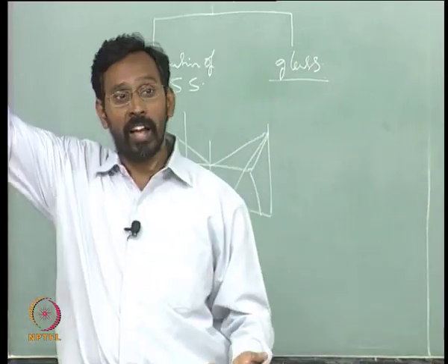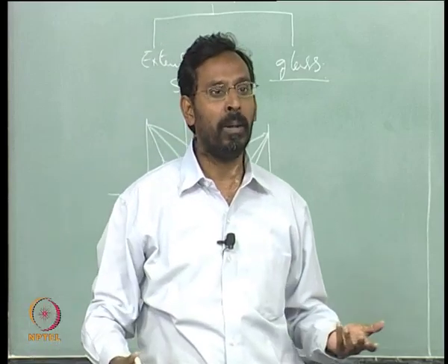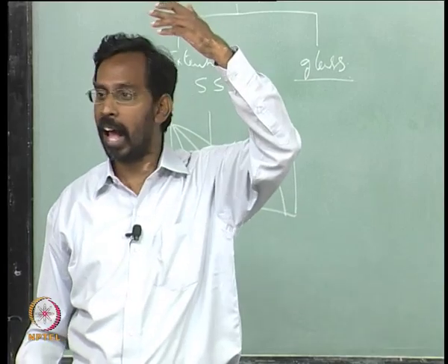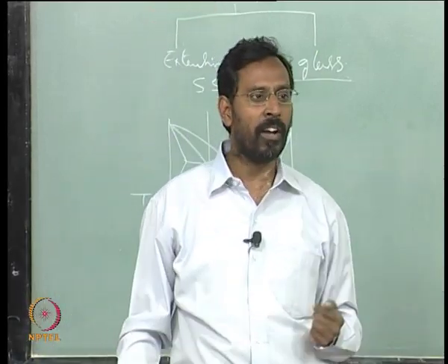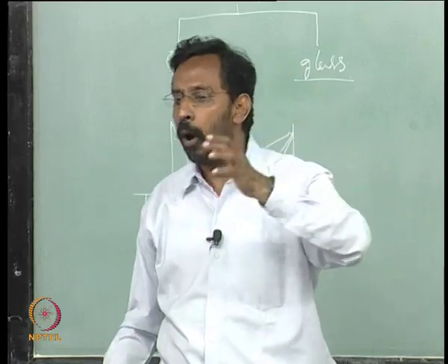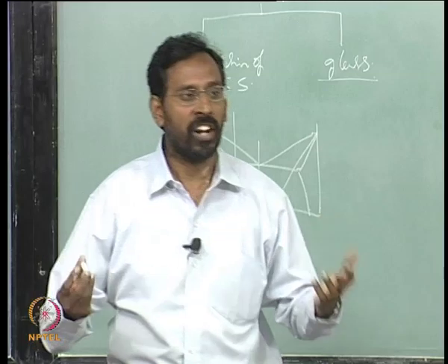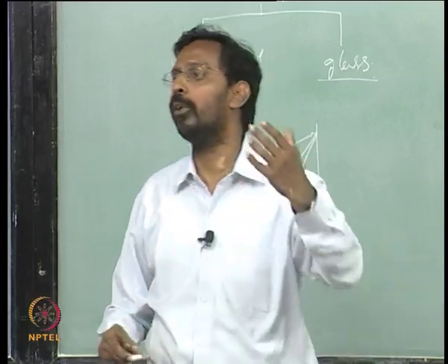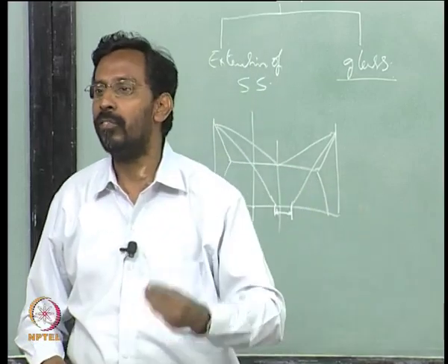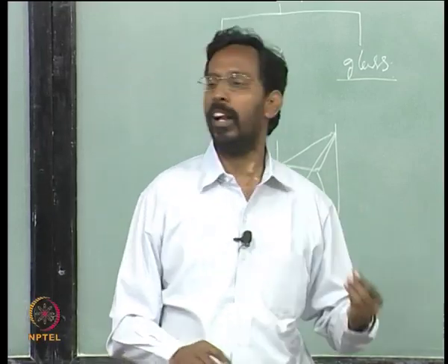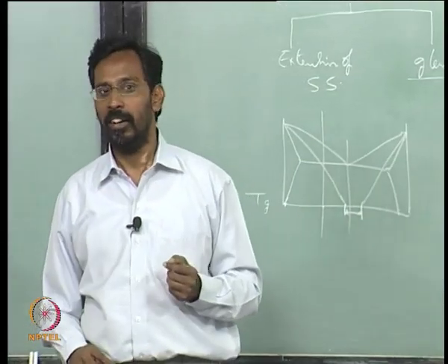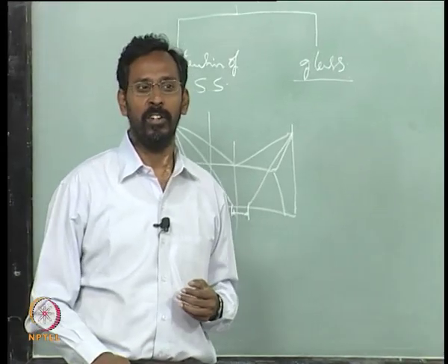Similarly, when a solid is becoming a gas by sublimation, you will see the delta H is much larger, because the enthalpy of the gas is much different from the enthalpy of the solid. So, the enthalpy difference is related to how much change in the structure is taking place from one to the other. Particularly if it is simply an FCC to BCC transformation, the delta H is usually very small. So, this is how we can see the delta H, whereas in a second order transition you will not see this happening.